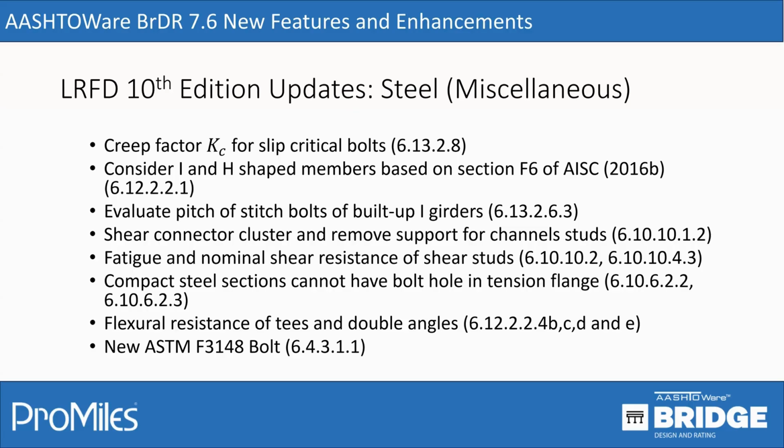There were some updates for considering pitch of stitch bolts for built-up I girders. Shear connector clusters were introduced. I don't have the screenshots here because of lack of space, but for shear connectors you can now define shear connectors in a cluster of 3 or 4.